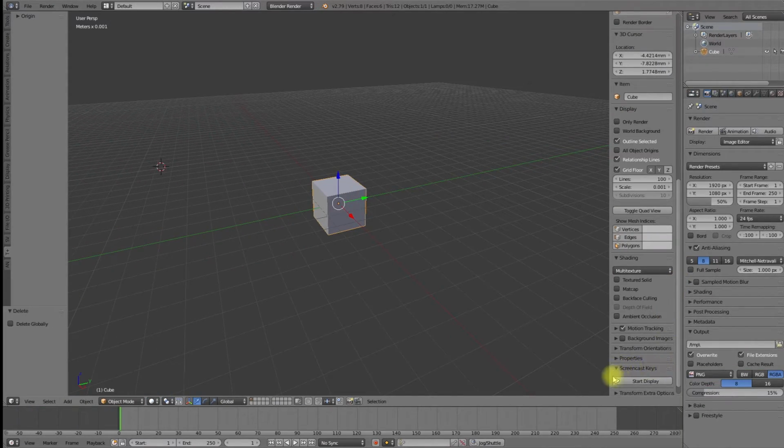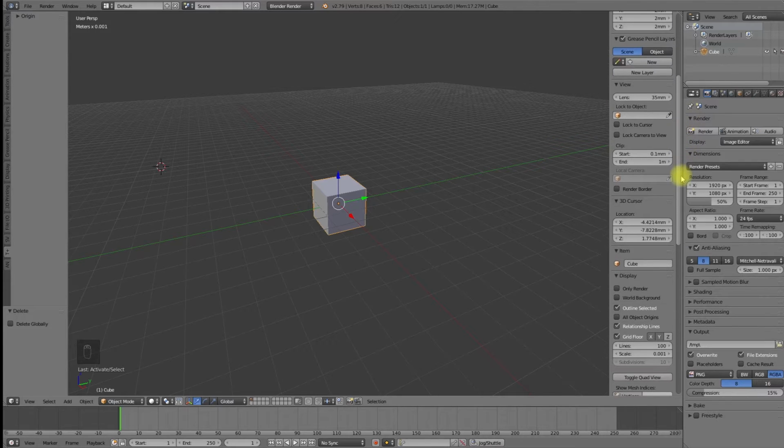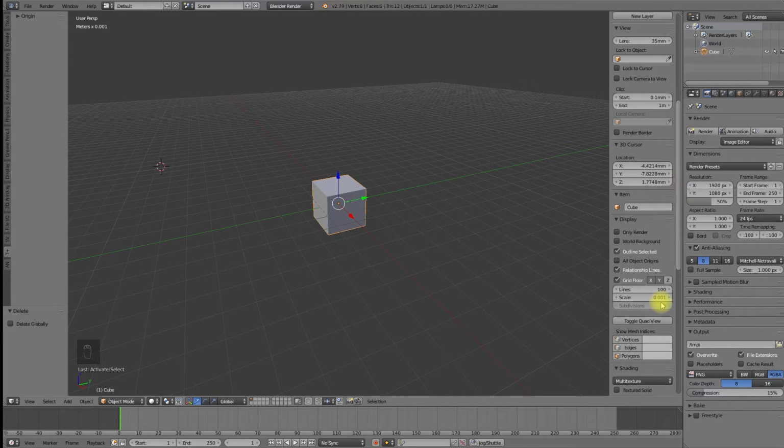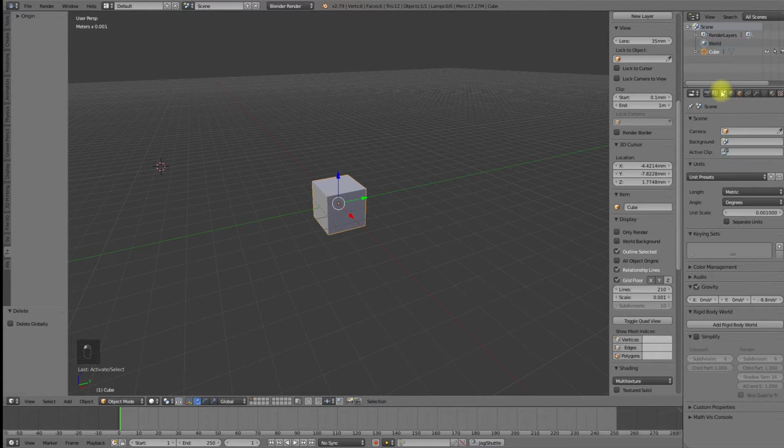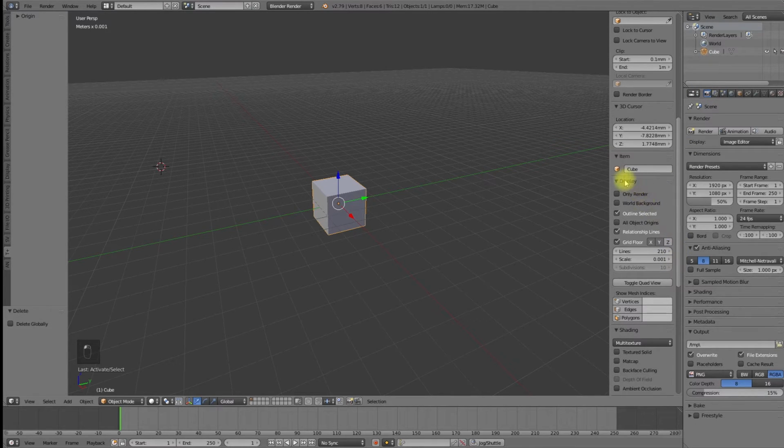In my case, it is a router template that I can use in the workshop. Keep in mind, in the same way as in my other videos, my scene settings in Blender are set to the metric measurement system and the 1mm unit. Also in the properties panel and display section, I set the grid size to 1mm, and normally I set the size of the grid to the size of my 3D printer print bed.